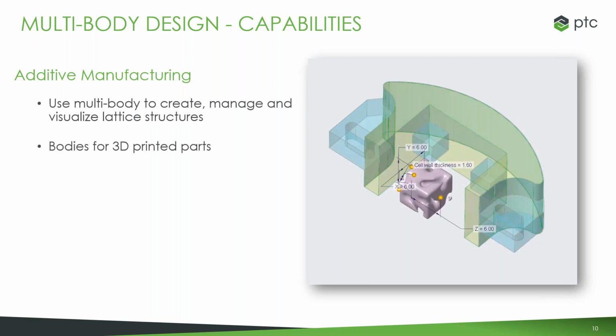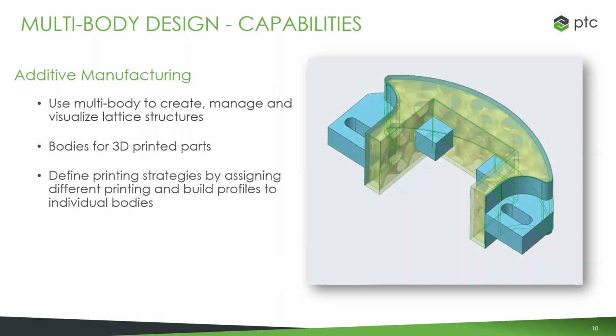It's also very easy for 3D printing. You can choose different colors, different materials for different bodies. Additive opens a lot of new options, where multi-body gives you the ability to explore that, because traditionally, a part gets one material definition, one color, right? And so if you want to print things with multiple colors, multiple materials, you'd have to have an assembly then, where with multi-body, no problem, change one of the bodies to whatever you want it to be that's different, send the part, just the single part file to print, and it will be able to take advantage of that.